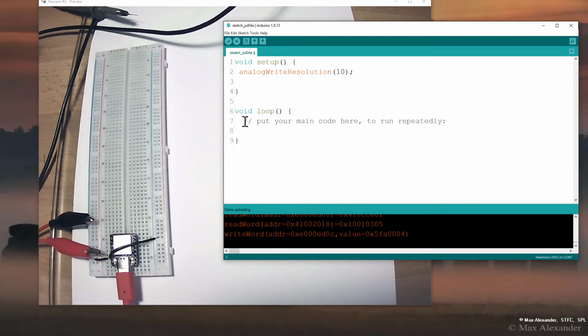Literally in this exercise, all we're going to do is write a value and then read the value. With 10 bits, that's a total of 1024 different levels, starting at 0 to 1023. Here's what we're going to do. Initially, we're just going to type in the bit level. We call these units the bit level from 0 to 1023 in the case of 10-bit resolution.